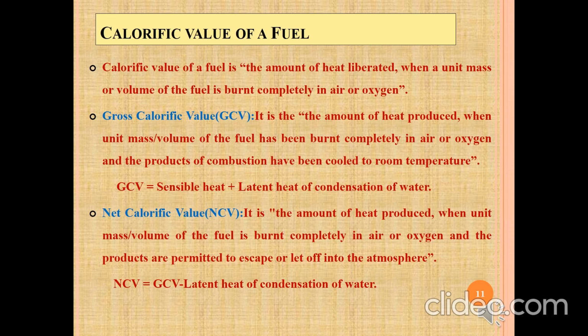Gross calorific value is nothing but the amount of heat produced or liberated when a unit mass or volume of the fuel is burned completely in air or oxygen and the products of combustion are cooled to room temperature. GCV is given as the sum of sensible heat plus latent heat of condensation of water. Whenever a fuel is burnt in air or oxygen, heat is liberated and the combustion products are formed. The heat liberated is nothing but the sensible heat. The products of combustion are cooled to room temperature.